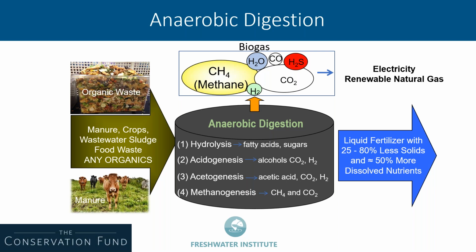In a similar manner, anaerobic digestion could also be used to convert aquaculture waste into renewable energy with mineralization of nitrogen and phosphorus. Mineralization basically means the process will convert organic nitrogen and phosphorus into plant available dissolved forms. Anaerobic digestion also reduces the pathogen content and solid concentration of the waste, sometimes up to 80% or more. In addition, it may also be possible to recover anywhere from 2 to 18% of the energy requirements for RAS systems from this process, which can also lead to additional savings for a production facility.